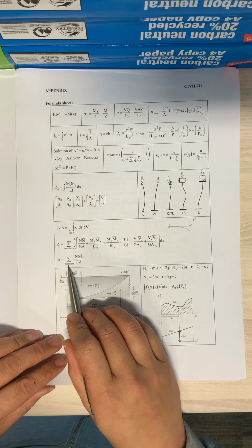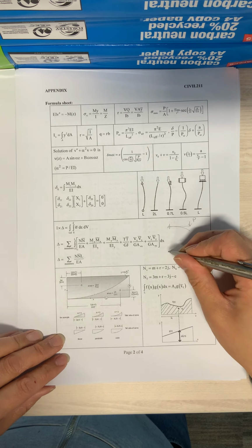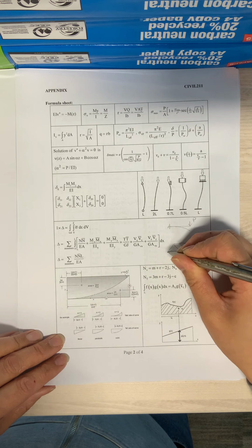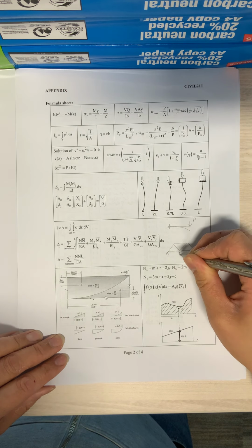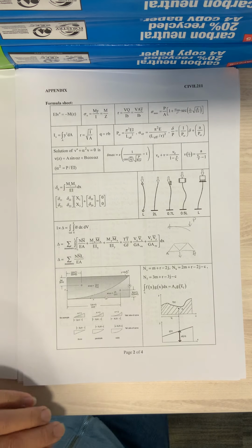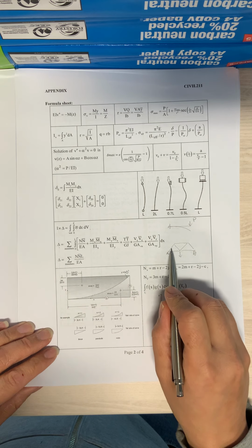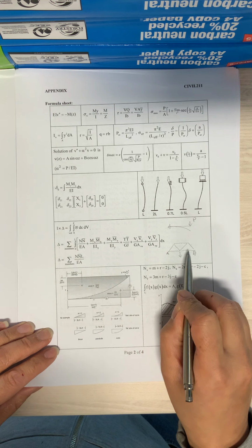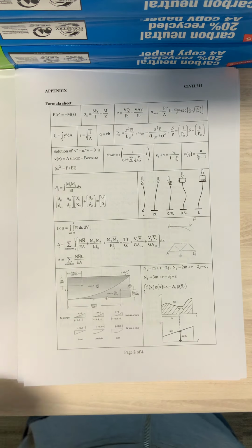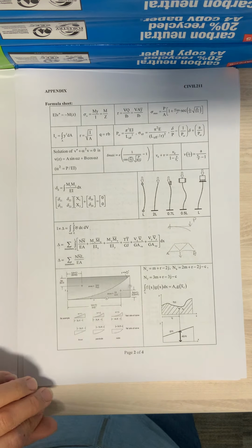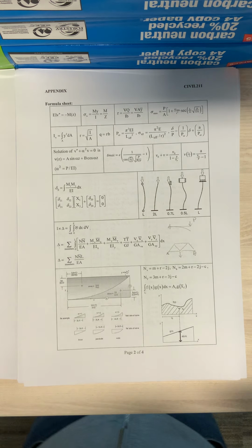And in the particular case of a truss, so that's not a beam, but it's a truss, and maybe you had a load there, for example, you could use virtual work, or this equation here, work out the axial forces in each of these members, work out the axial force in another compatible situation, and then use this to be able to work out what your deflection is.